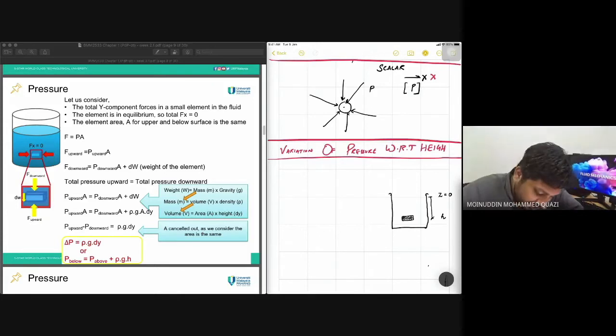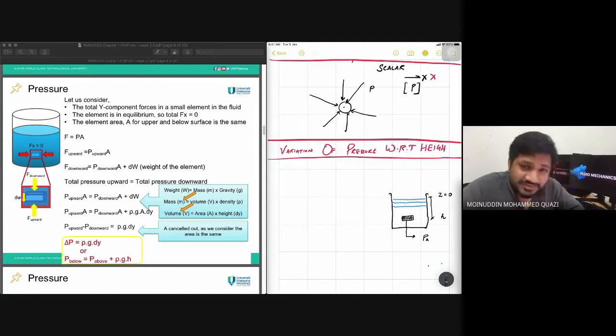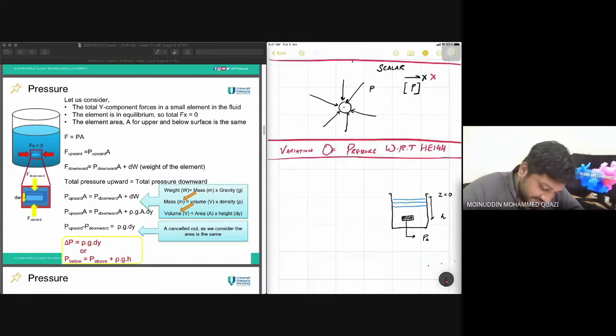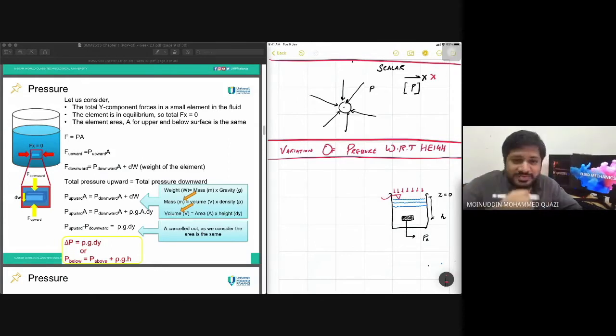Now I want to know how much pressure is acting on him. He is completely in a sea or in a fluid. He is diving in a fluid. The fluid can be anything: water, sea water, lake water. All have different properties because they have different amounts of salt inside. Now because he is swimming in, let's say, a sea or some lake, we have atmospheric pressure which is acting on the surface of the lake or pool. Atmospheric pressure is denoted by this inverted delta. This is the indication that atmospheric pressure is acting.